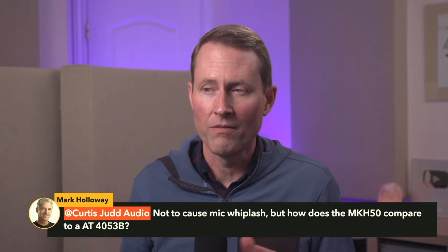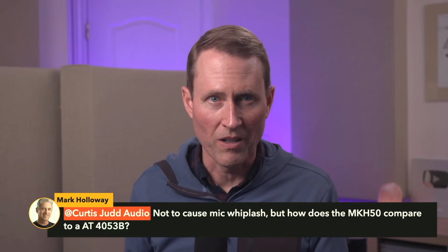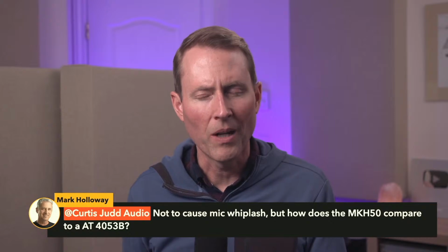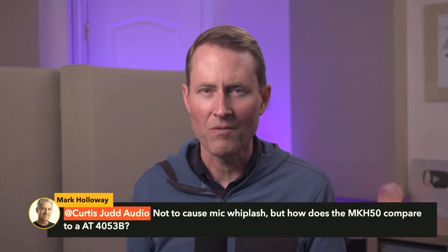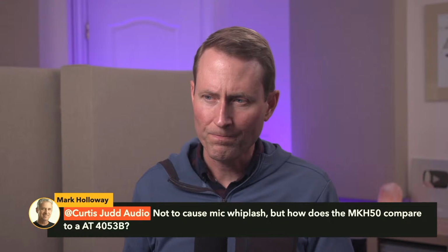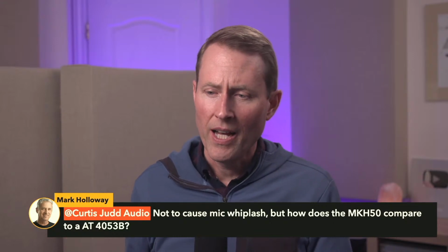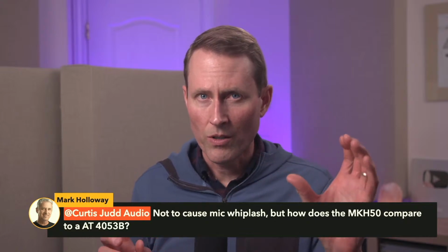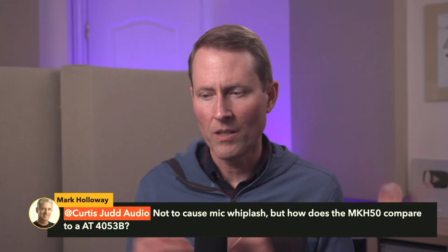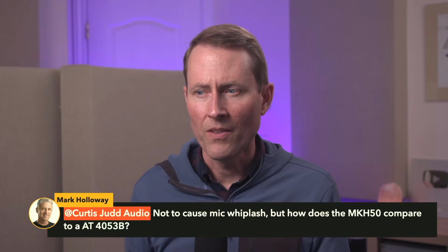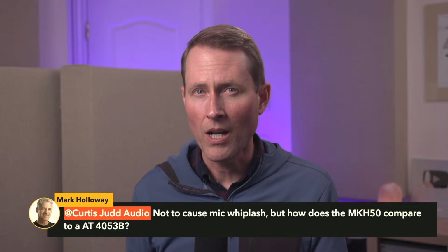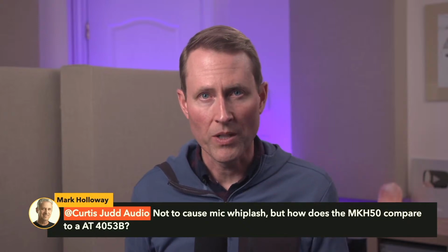What's the output impedance of each of those microphones? How does that compare to the input impedance you have on your MixPre? You're probably going to be fine with any of them, to be honest, with a MixPre. Another thing that you'll see, a big part of the reason why the Zoom F-series recorders are less expensive than the MixPre is that the headphone amplifiers in the Zoom recorders can't supply as much output.